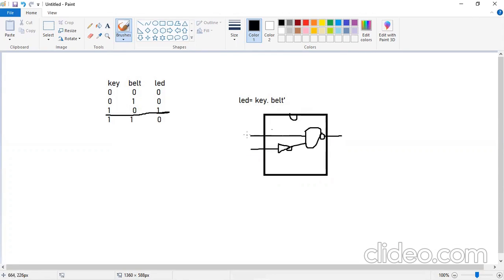So these are the two input ports and this is our output port. This is called the port list. But suppose this NOT gate is connected with this AND gate input, the NOT gate output is connected with the NAND gate input. That will not come into the port list, because it is not a port of your IC, right?